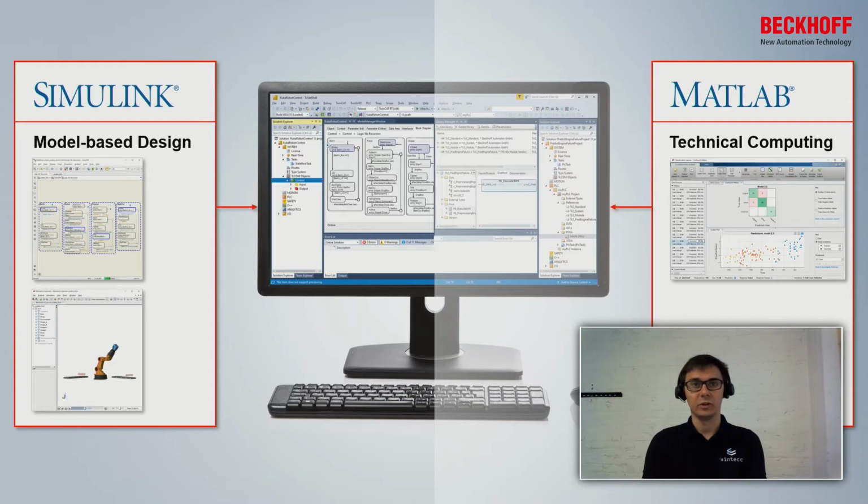The second one is you can see a representation of the Simulink model straight in TwinCAT, so you can follow all the signals in real time. A third advantage is that you can also connect the TwinCAT system with external mode to the Simulink model, so you can follow the execution of the Simulink model in Simulink whilst being connected to the target. And the last example is for me that the target for Simulink integrates well with Simulink, so you can find all the code generation options straight in the Simulink settings.